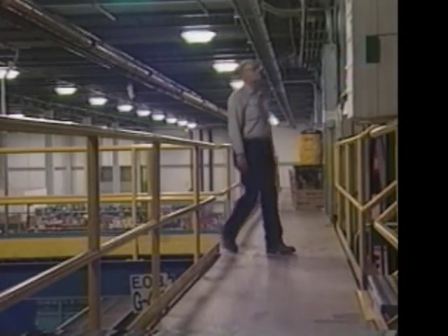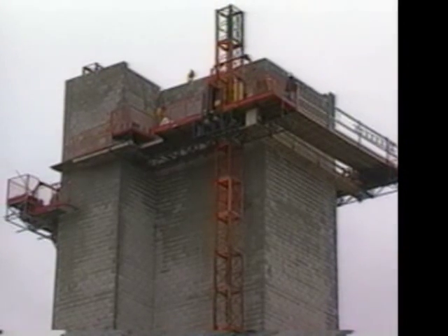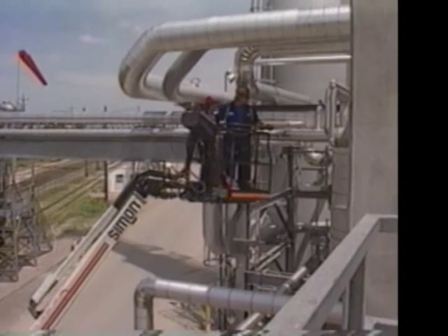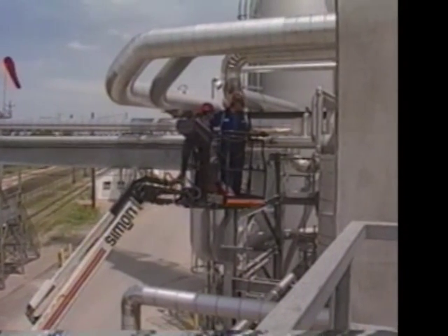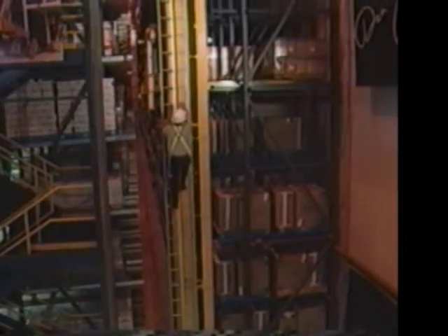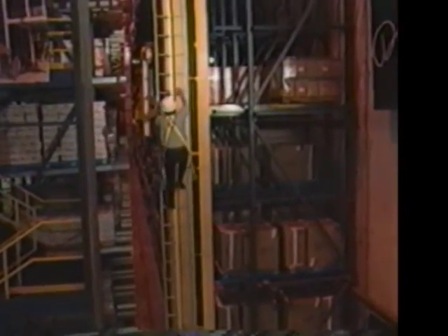Since every fall hazard cannot be eliminated, respecting the hazards and following safe work practices is essential for eliminating accidents. When possible, engineering controls such as guardrails, scaffolds, and aerial platforms should be used. These devices offer protection from falls and can also safely elevate the work surface to the desired height. When it is not possible or feasible to use such devices, a personal fall arrest system must be used.